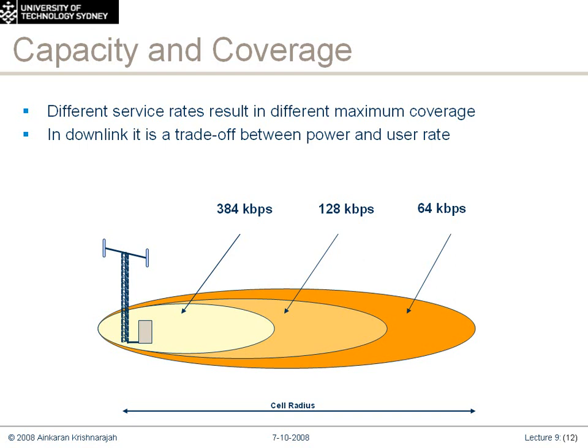For the capacity component, how does power of the base station impact capacity? In order to run each service, whether it's voice, packet data, say at 64 kilobits or 384 kilobits per second, each of those services will require a different level of power from the base station in order to operate properly. So the higher data rate services will actually take more power, and the lower data rate services will take less. So voice services typically run at 12.2 kilobits per second. So you can generally fit a lot of voice services into a mobile cell. But if you have a lot of people using high data rate packet services as well as making a lot of phone calls, then the base station tends to be very loaded.